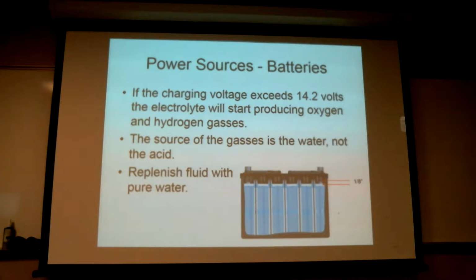Okay, if you've got a pretty low battery, not completely dead, but pretty low, get the engine pop started or jump started, and then your generator starts generating, it's hitting it with pretty high amperage. It's not the best thing in the world for the battery at all.